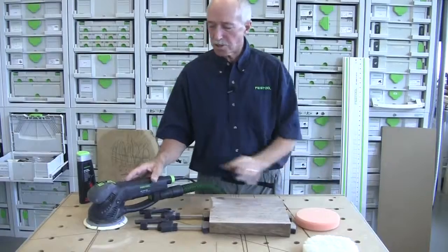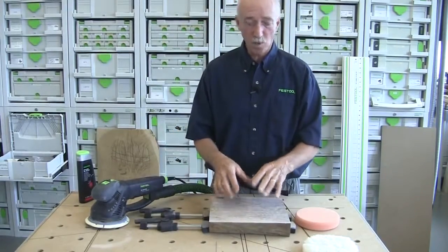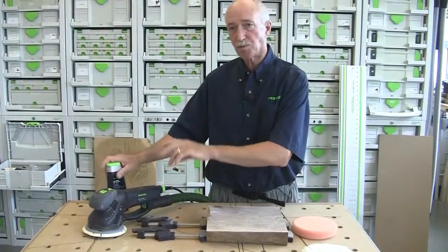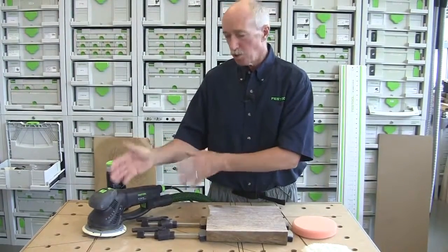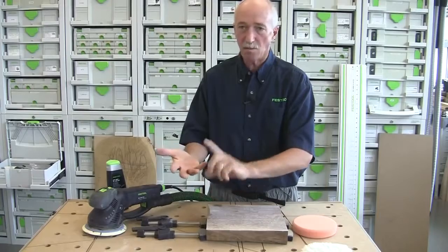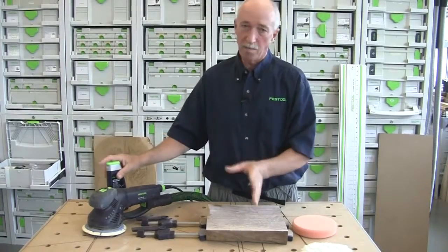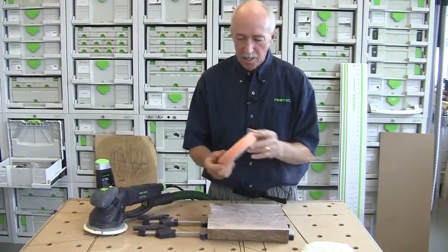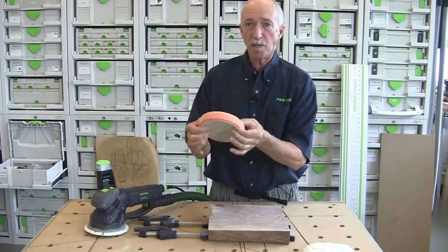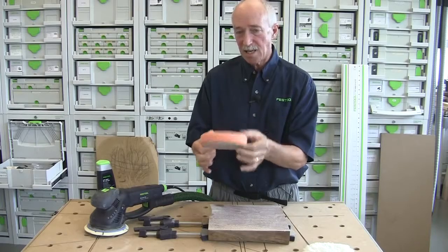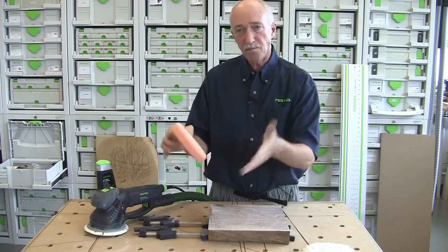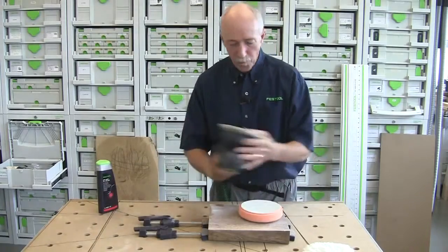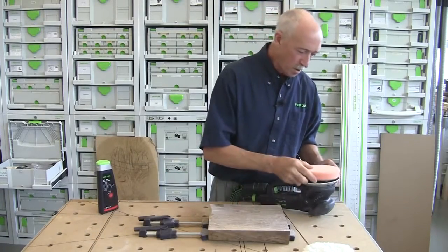Now we're going to use the Rotex sander to do some polishing. We're going to apply polish, and then we're going to buff it out using this machine, which is really the 3rd application we can use with this machine. It's not only a fine sander, a rough sander, but it's also one of the best polishers I've ever used. So to start the process, we're going to use what we term our orange sponge. It's a medium density, and it will allow us to get into different cracks and crevices, but it'll also work good on flat surfaces. So we put this on just like our sandpaper.